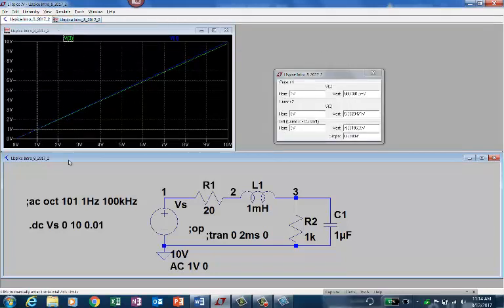Look at that. This is what I have now. This is the input and output. You can see the gain of the circuit. It is like 0.6, almost 6, because there's a potential divider, and most of the voltage is the output there. Now if you change the values here, the R1, say maybe 200, the gain will be less. This is the DC transfer sweep you can have.